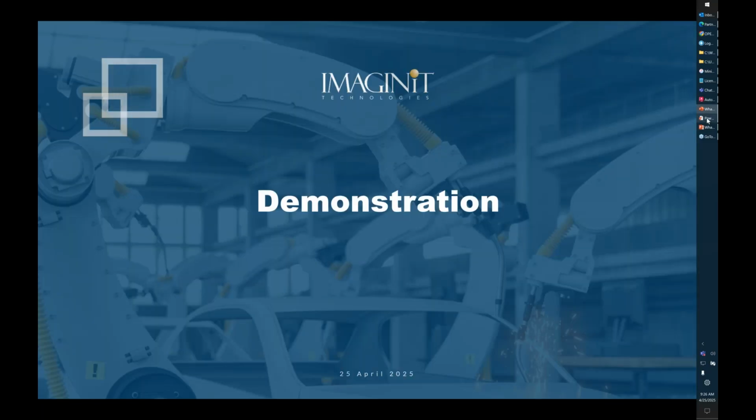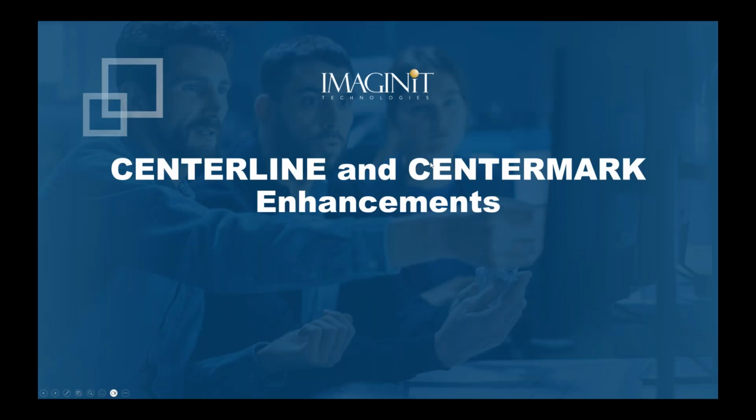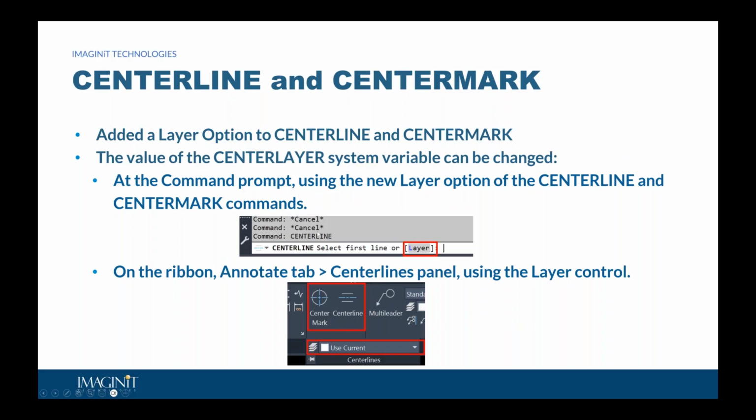All right, now let's talk about the CENTERLINE and CENTERMARK enhancements. This is something we've asked for on the mechanical side for years. There is now a layer option when you do the CENTERLINE or CENTERMARK, and the center layer variable is now a new system variable that can be changed to specify a specific layer at the command prompt using the new layer option of the CENTERLINE and CENTERMARK command.